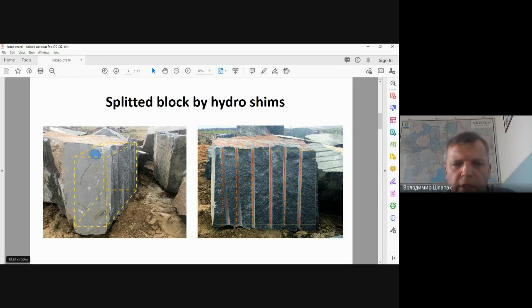When using fracture forming methods, the deflection of the borehole axis causes a change in the geometry of splitting forces spreading, affecting the efficiency and quality of the splitting and separation process. Borehole deviation when performing drilling operations in a stone massive can cause increased separation area, tool costs, and poor quality of